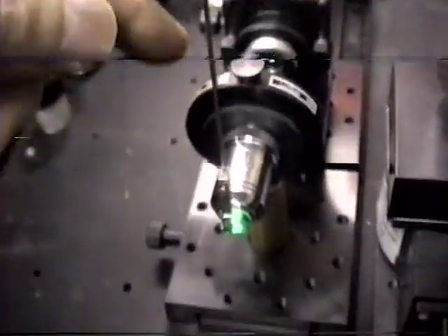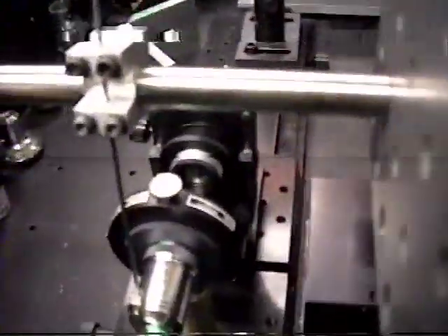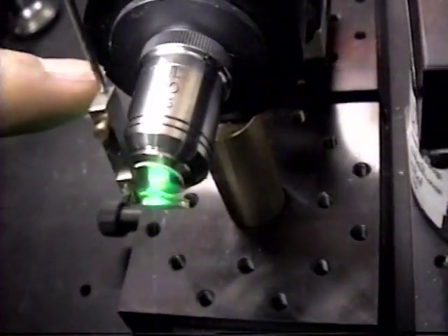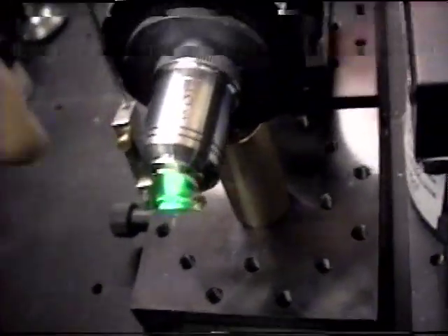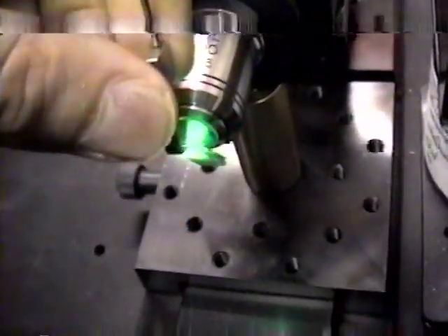It's more rigid than the smaller size tube, and also the bigger size tube is big enough to accommodate the jacketing that goes over the fiber, whereas the smaller size tube cannot accommodate the jacket, and only the cladding can stay on the fiber, because the fiber itself really has three layers. It has the core, the cladding, which is sort of like a rubber almost, and then this jacket, which is probably Teflon.